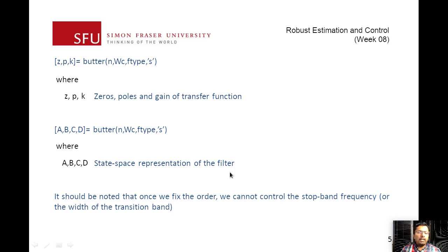It should be noted that once we fix the order, we can't really control the stop band frequency or the width of the transition period. All of that is entirely determined by the order of the filter that you choose.